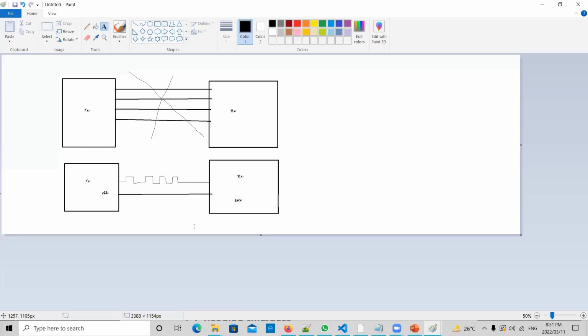USART or UART, they used to call it. That serial communication that was implemented initially can transmit only 1 byte in one packet. They will transmit the data frame by frame. When they want to transmit 8 bytes of data, they will put that in packets and send it out.